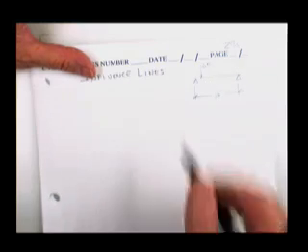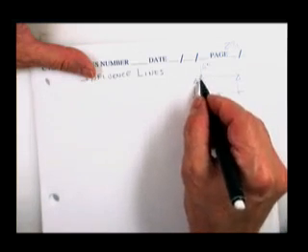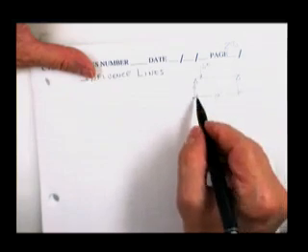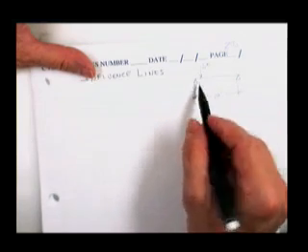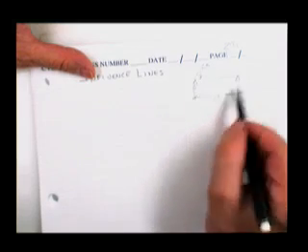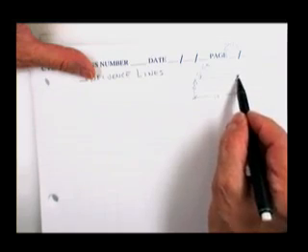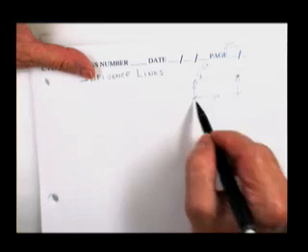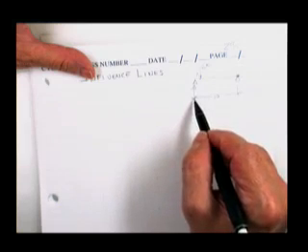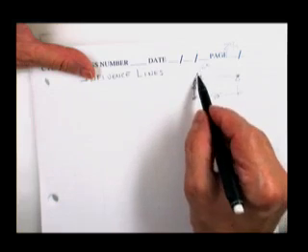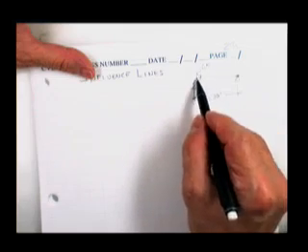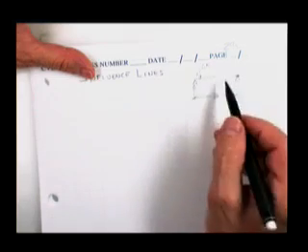To cause the biggest shear, for instance, right now with a 6 kip over here looks like about 2 feet, you're going to get, if that is 2 feet, I would sum moments about this right reaction, 6 times 8 minus this reaction times 10, and I notice the reaction is reduced from 6. But if you back it up so it's 9 feet away from here, then you got 6 times 9 minus the reaction times 10.